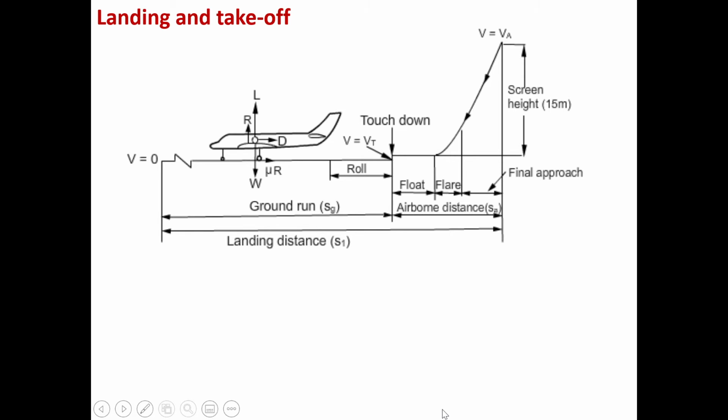Sorry. So you have the final approach distance. You have the flare distance, which is equal to the transition distance when you are taking off. We have an additional distance when the aircraft is floating, but it's not on the ground yet, right? So essentially it is on the ground, but it is not on the ground, meaning that the thrust and weight are basically equal and the aircraft is moving just, let's say, 1 millimeter above the ground, right?